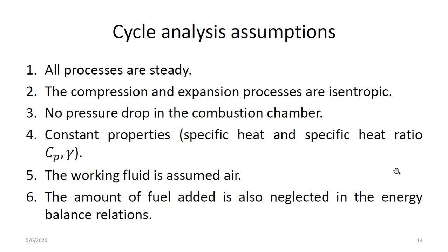Now, for an ideal cycle, if we make a cycle analysis, we can assume the following. All processes are steady. The compression and expansion processes are isentropic. There is no pressure drop in the combustion chamber.